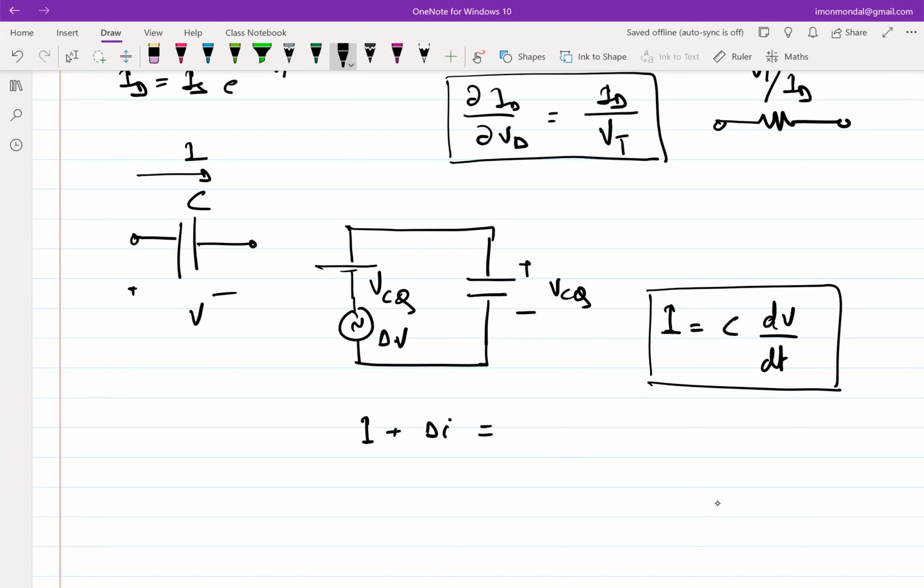Not really, right? So this is not the fundamental relation between capacitance and IV of a capacitance. This is a fundamental relation of an IV of a linear capacitance. Okay, step change in the voltage. Even if you have a step change in the voltage, this still holds, right? dV dt probably will be infinite in that case. We assume the capacitance is constant. The relationship actually is I is equal to C dQ dt, right? Under the assumption that capacitance is not changing, then you bring the C term out, right?